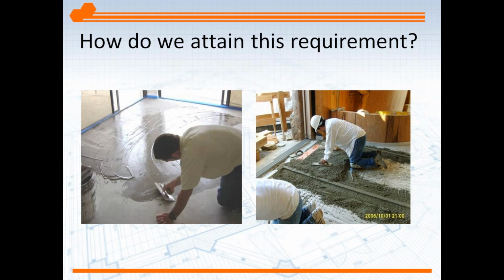You could also create a mud bed if you have the height capability or if you have the weight capability. You can see this is what's called a cleavage membrane mud bed, which is a pretty deep mud bed with fiber reinforcing in the middle. It's an unbonded mud bed. It has a plastic underneath it to keep it from bonding to the substrate. It's just one type of mud bed, the type of mud bed we would use above grade, but it's an example of a mud bed. If you have, like I say, the depth and the weight to do it, you can level a floor this way.